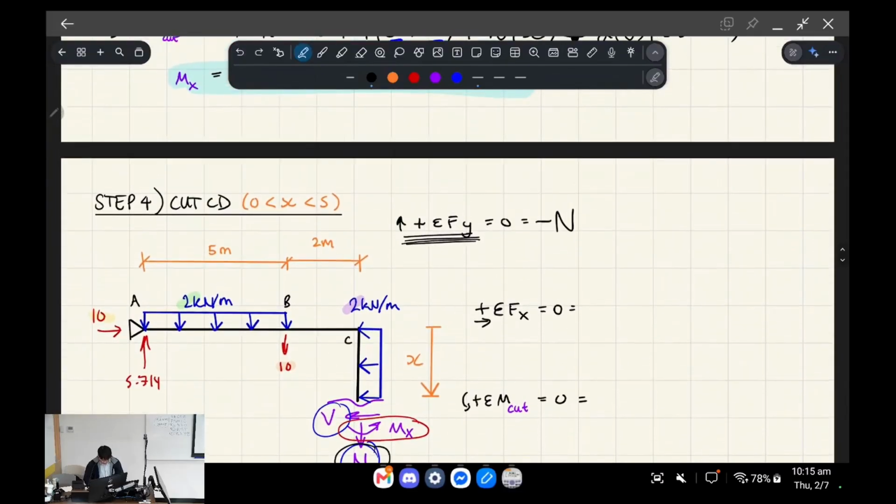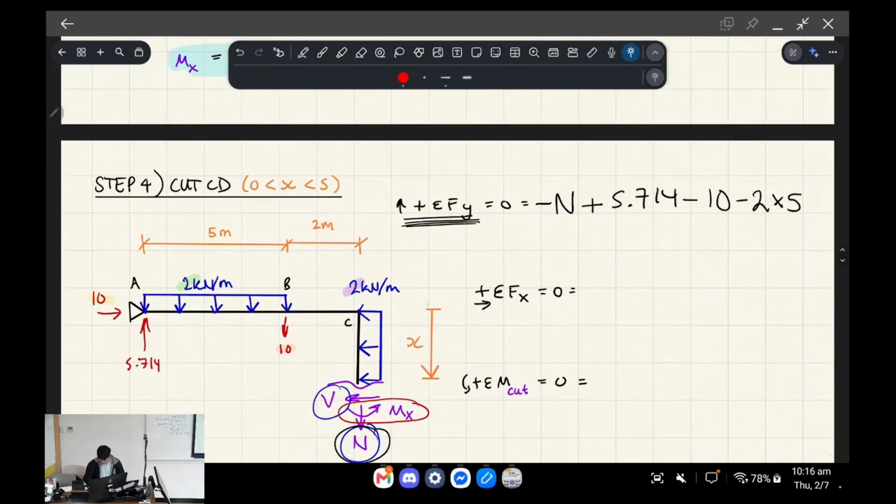The second thing is that instead of considering the horizontal forces like we had before for axial force, like the 10, we're looking at all of these vertical ones now. So all of these vertical ones are going to result in a much different axial force. As a matter of fact, this is essentially the main difference between beams and columns. A beam, being a horizontal member, looks at the horizontal forces when considering its axial forces. But for a column, to consider its compression, you have to analyze gravity loads that enter the column. Does that kind of make sense?